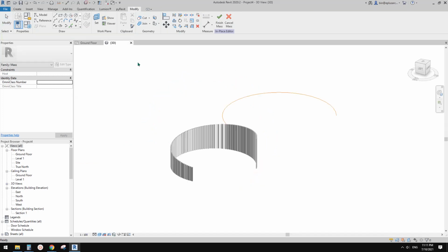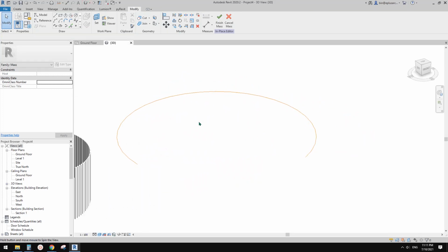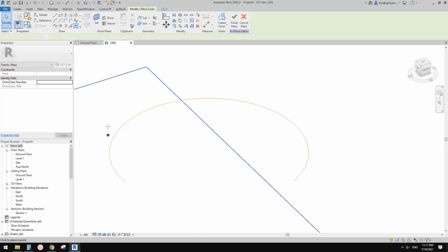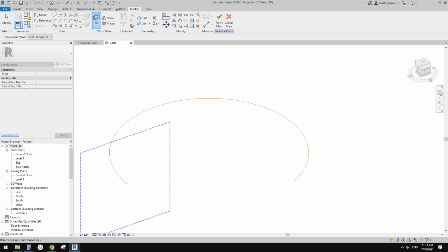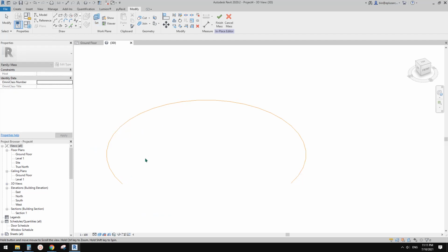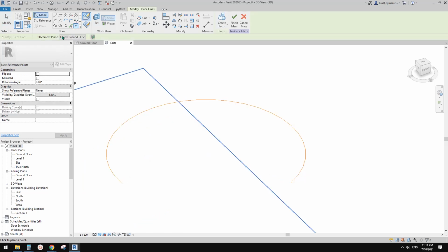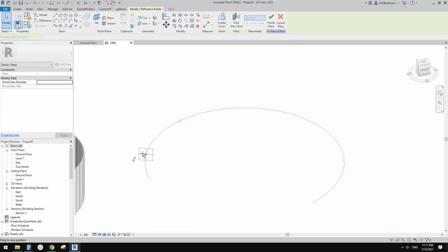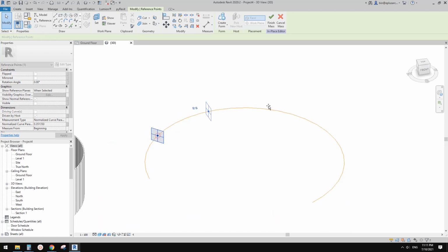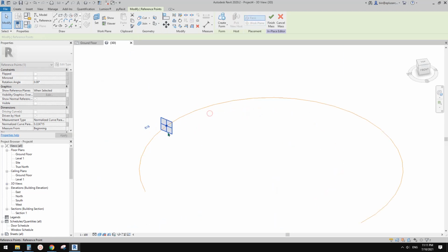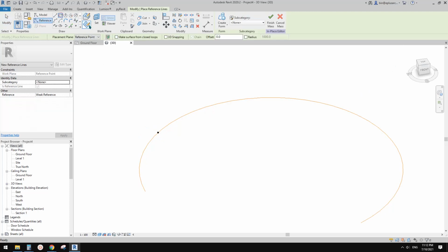So now let's go to 3D view again. So for this, I like to place a point. Actually, you can directly draw a profile on the work plane of this end. So you can see you can place a profile here, but I like to do it this way. So I like to place a point. Use draw on face, so this point can be moved around. So you don't need to start from here. You can even start from the middle. Okay, anywhere. So now we have this point, we can place a profile on this.